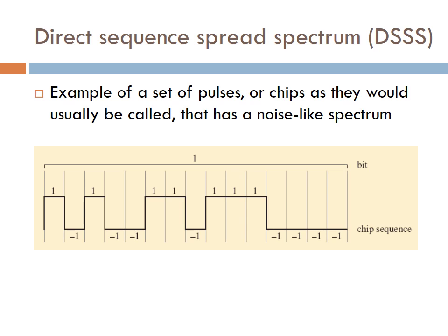For receivers that do not know the codes, the transmission just looks like noise, and if the transmission power is not too great, the existence of the transmission can pass undetected. For these reasons, DSSS has found its first uses in military communications. However, the technique is widely used in non-military applications, and the development known as complementary code keying is used in the 802.11b Wi-Fi standard.